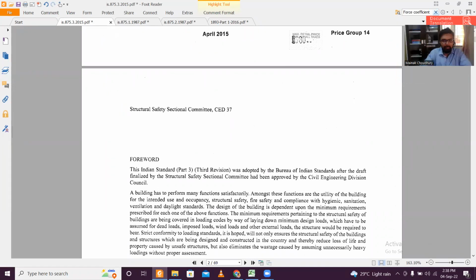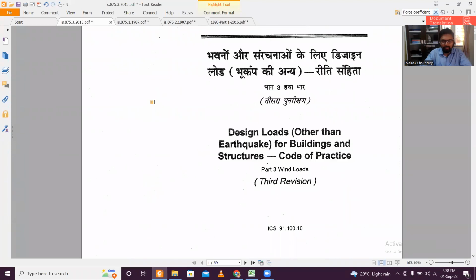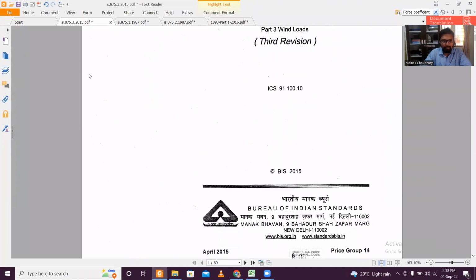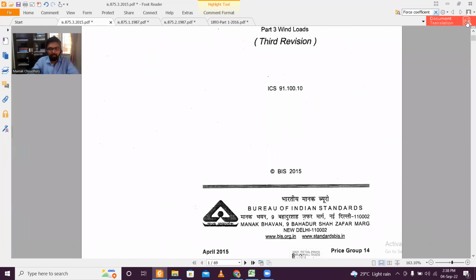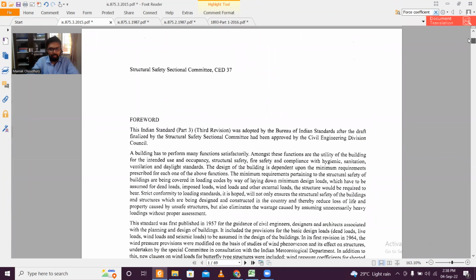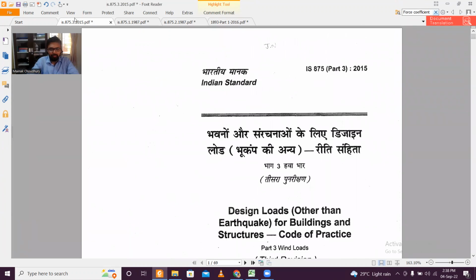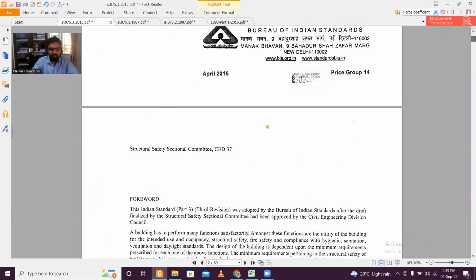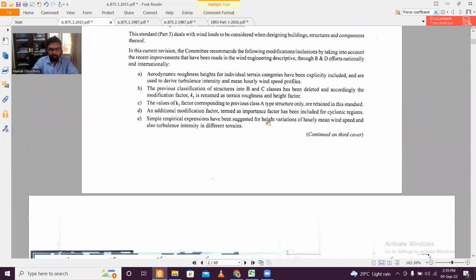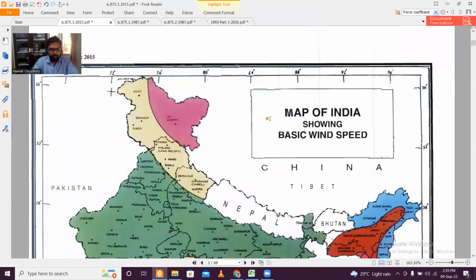On YouTube you'll find many videos explaining the code provisions, but they are old ones. The latest ones you might not find till now. So make sure you download IS 875 Part 3, 2015, because it's the latest version, and you should always follow the latest version of the IS code which is available, right? So moving on, we will start the explanation.